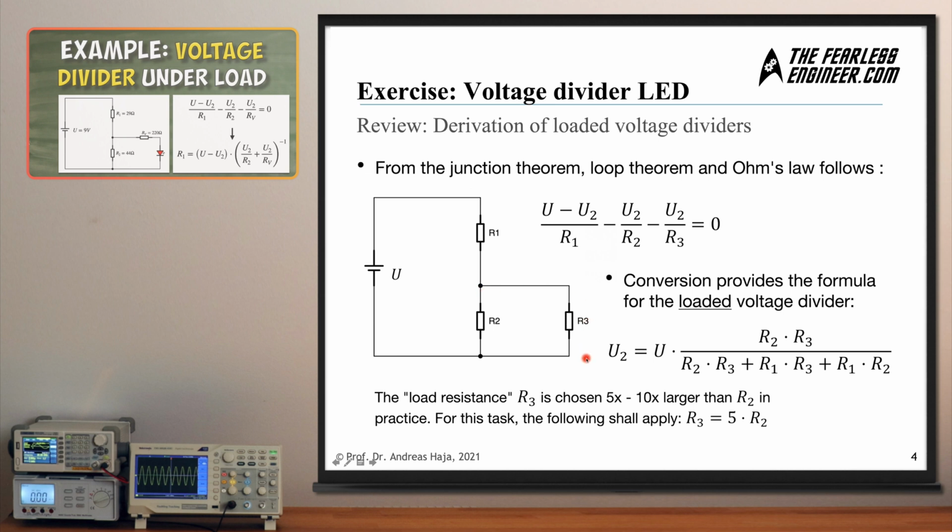And this resistor number 3 means that a certain fraction of the current flowing through R1 is also directed across R2, which also means that the current flowing through R1 is different from the current flowing through R2. This renders the original base equation of the voltage divider useless in this case, because it is based on the assumption that the current flow through both is identical, which is not the case here in